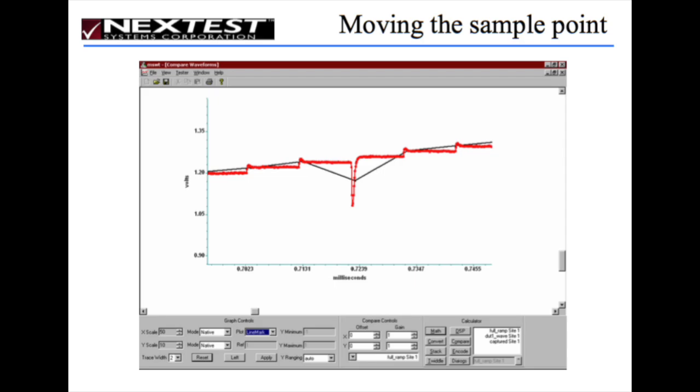And this is a good start. It's not the way to solve the problem, but we can trigger it at any vector we want. So we trigger it one vector later, and we're not at the peak of the glitch, so it doesn't look as bad. So we simply move it over. We can move it by one T0, one cycle, or we can move it a little bit with a delay. And that's how you do it. You fine-tune it so that it works the right way.